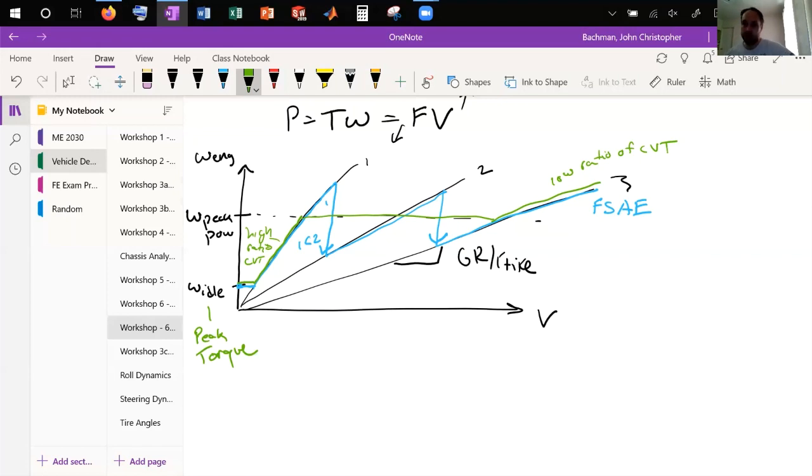I mean, you see why the CVT is such a beautiful system, but it deals with belts, right? And so you lose a lot of efficiency through the belt, basically. So that's why you probably wouldn't run this system on a really high power system, but it's also light. So that's why Baja likes it.